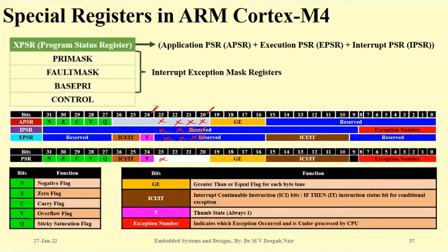So this kind of detail, if you want to check, for example, you get some error, assume you are running a program and you got an error and the program is stopped, or the microcontroller is halted. Now you have to check because of which error my microcontroller is getting halted. So you have the option to go to either of these three registers and check which bit is causing that particular error, right?